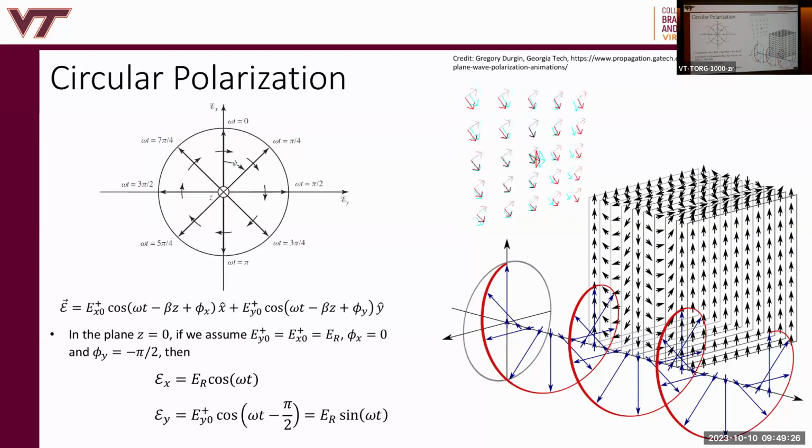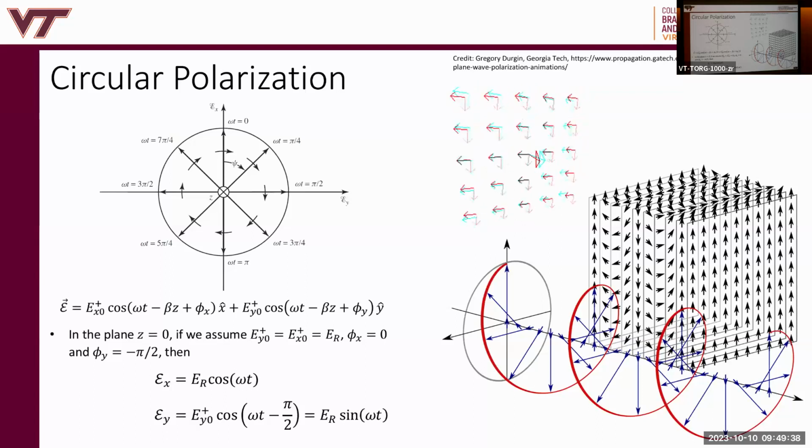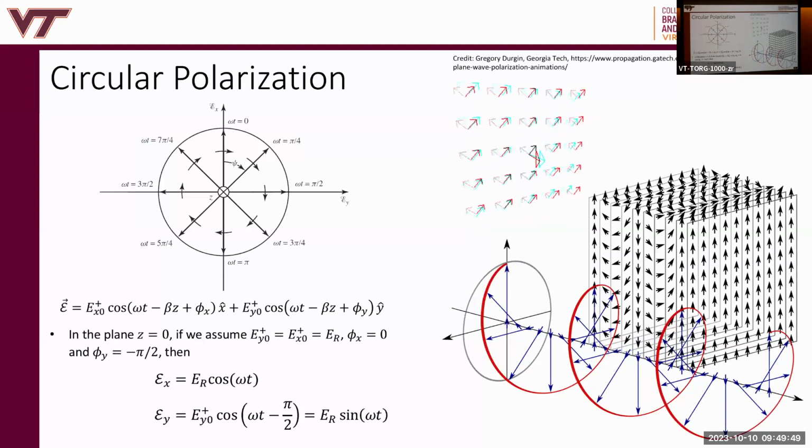One common use of CP is, say you have some satellite or a communication system that is transmitting or broadcasting electromagnetic waves like cellular systems, right? Normally those are CP. And why? Because your handset, it's not guaranteed. Your handset sometimes is linear polarized, right? And it's not guaranteed how you're going to be holding it. So let's say that the base station was vertically polarized. If you're talking on your phone like this, you're going to get no signal. So if it's CP though, and it spins, no matter what orientation I have my phone in, I'll get at least 3 dB down, right?